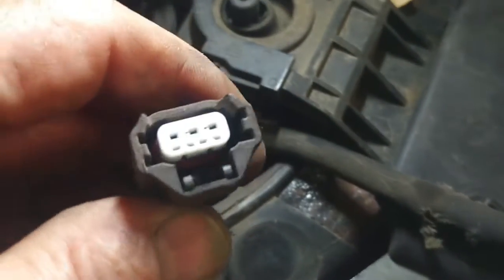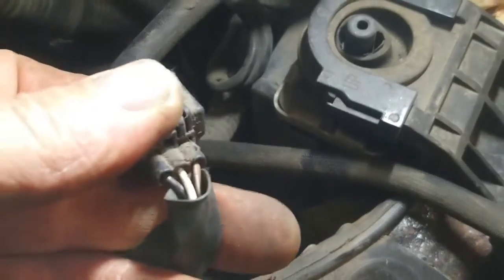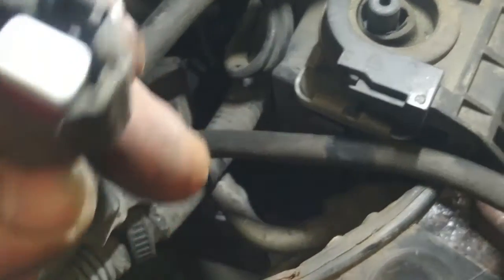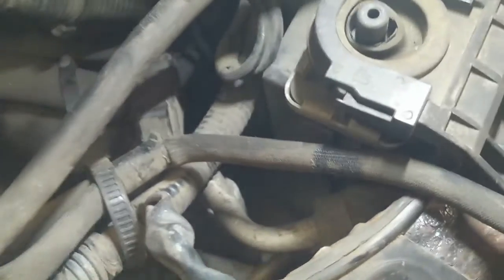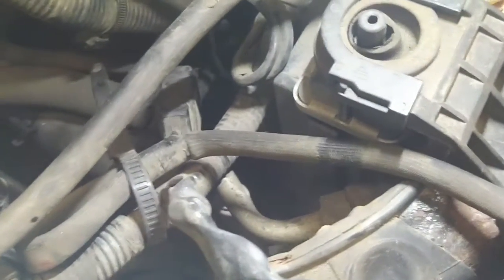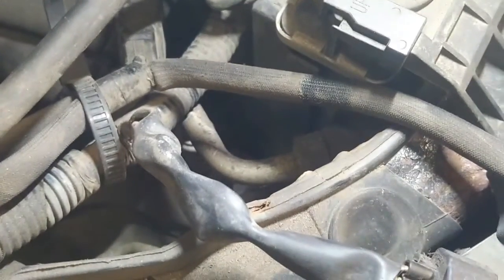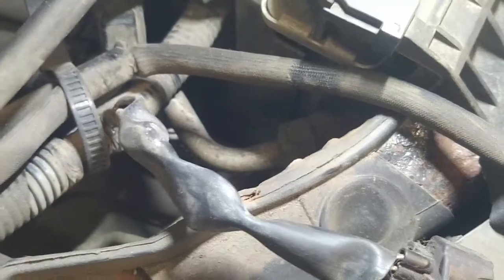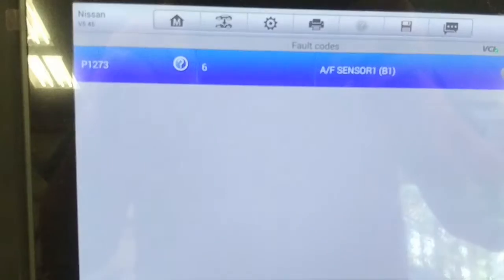So it's a typical 3-wire pressure sensor connector. The wiring looks good. I don't see any corrosion. I did unplug it and the compressor quit immediately. I'm curious as to whether or not it'll set a code in the ECM for the pressure sensor being out of range. It theoretically should, and if it does set a code, then theoretically there should have been a code if this was our problem.